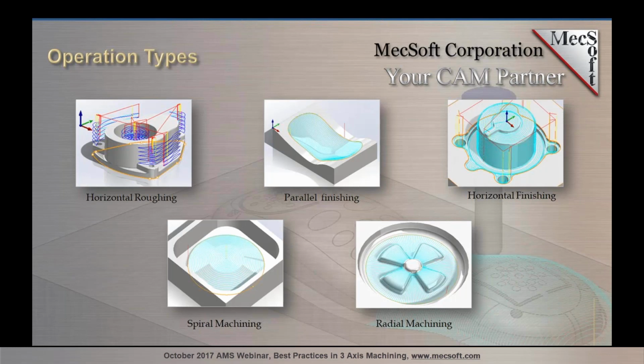There is an option called clear flats in your cut level tab, and Uday will talk about that a little bit. But that can be used for clearing horizontal sections. And again, as I mentioned earlier, there are a lot of tips and best practices available in the blog as well, so you can reference that for the horizontal roughing operation.